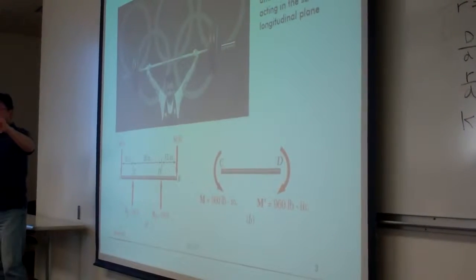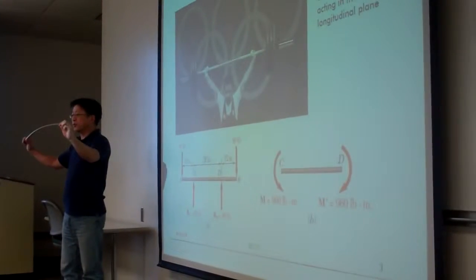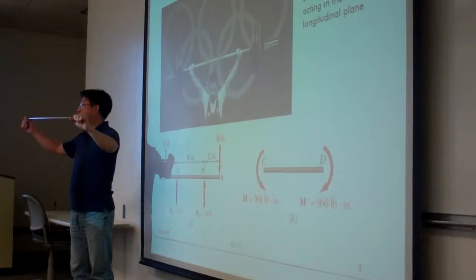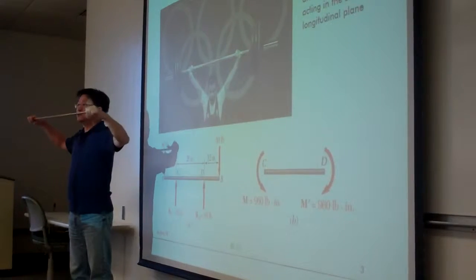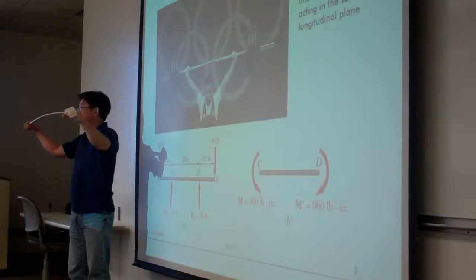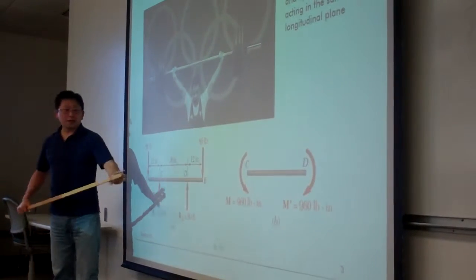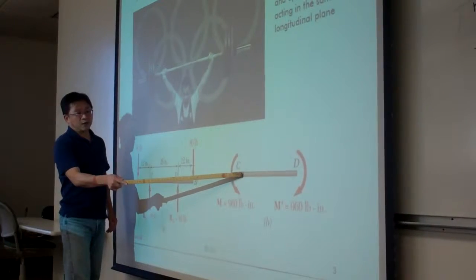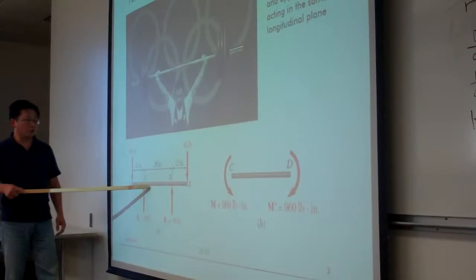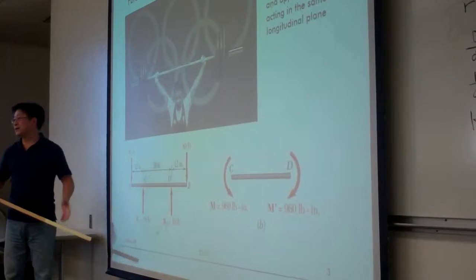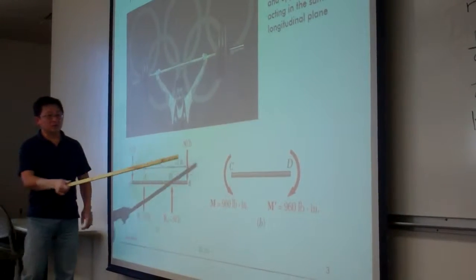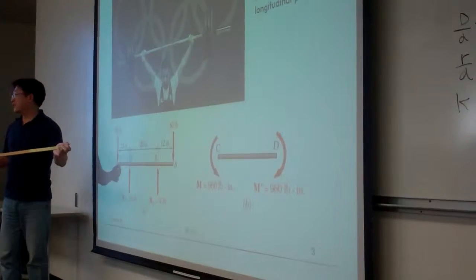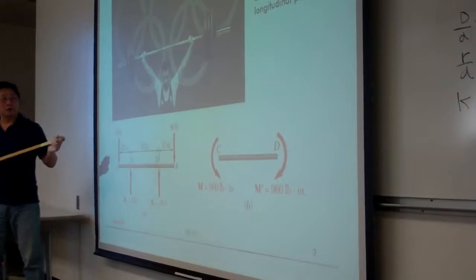So that is our story here, and the bending basically is this. And from now on, we talk about bending under pure bending. Basically, we will take up this model. So assuming we just apply the moment at the two ends, in this way that will give us the pure bending scenario, okay? And again, you should remind yourself, this is a generic model, and this could be a portion of the whole structure like this, or more complicated. Okay, so again, this is our generic model. We're going to use this model to develop the necessary formulas for describing this kind of loading situation.